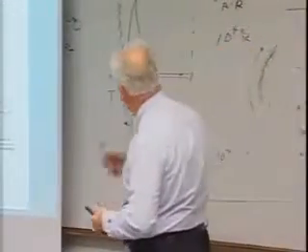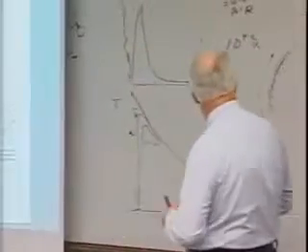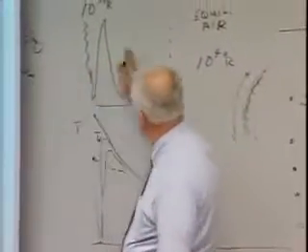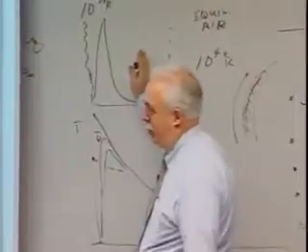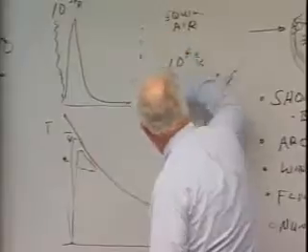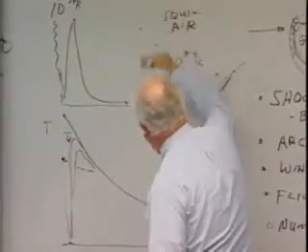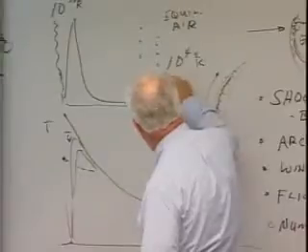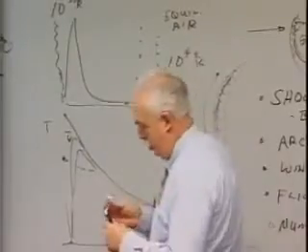Okay, surface catalysis. First order, start with molecules in the free stream, atoms, some ionized, and then I get to a surface back here. At equilibrium, I'm back to molecules again. They're pretty hot, but they're still molecules.